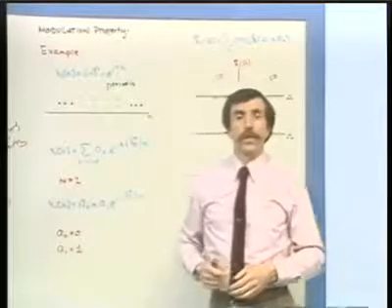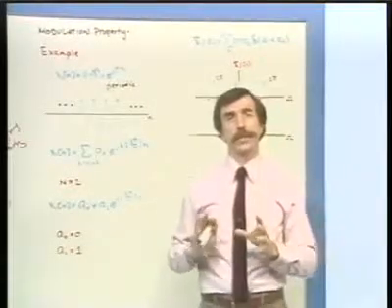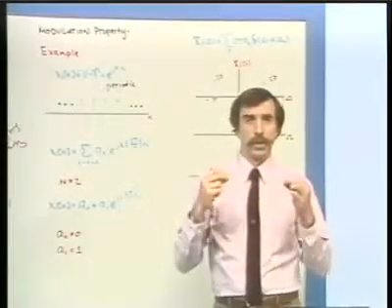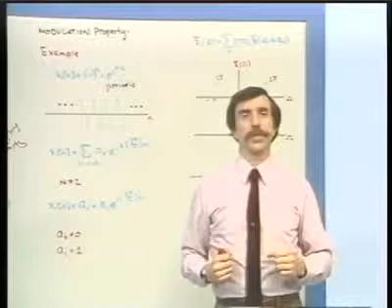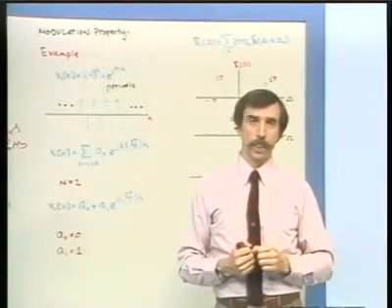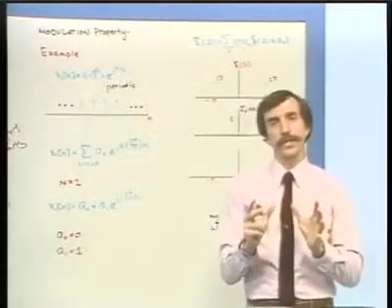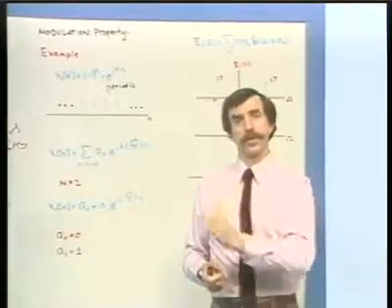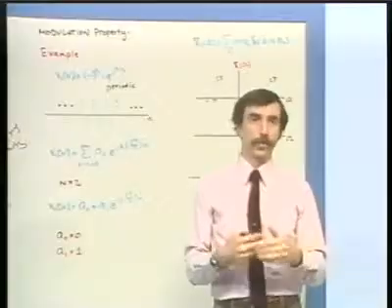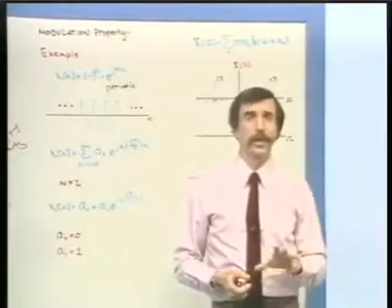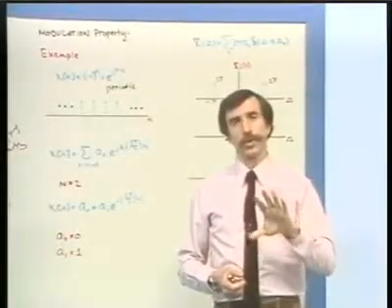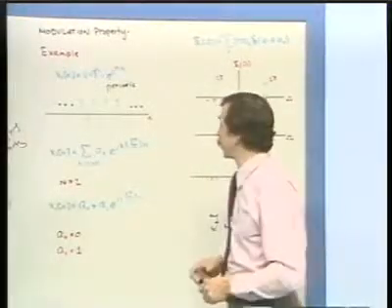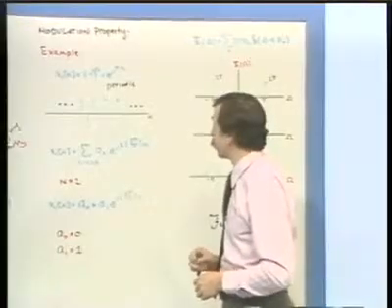And recall that to get the Fourier transform of a periodic signal, one way to do it is to generate the Fourier series coefficients for the periodic signal, and then identify the Fourier transform as an impulse train, where the heights of the impulses in the impulse train are proportional, with a proportionality factor of 2 pi, to the Fourier series coefficients. So let's first work out what the Fourier series is, and for this example, in fact, it's fairly easy.